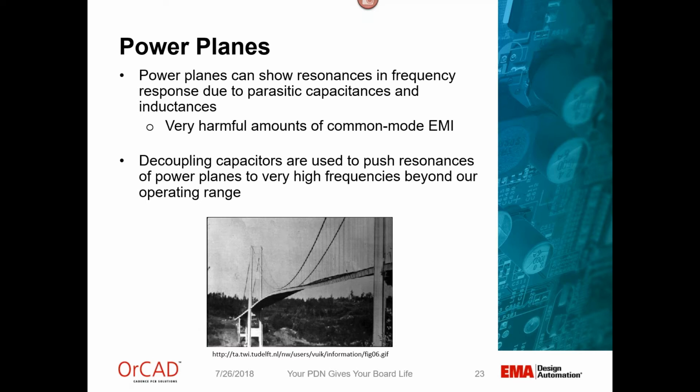Back to our very beginning table, we talked about resonance. And just like bridges, power planes can suffer from very destructive resonance if we don't control it. Just like with bridges, which are tacked down by those towers there, we use decoupling capacitors, decaps, to push the resonance of our power plane to a very high frequency to avoid that very destructive EMI.